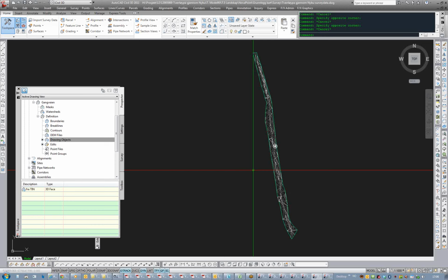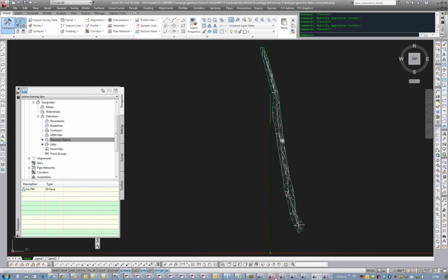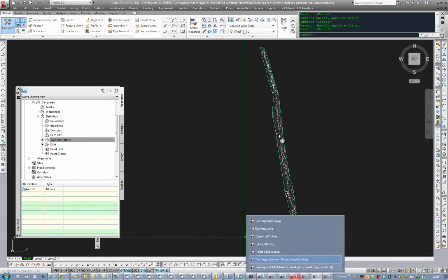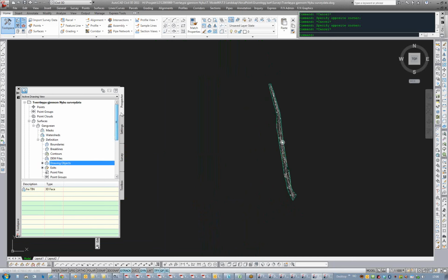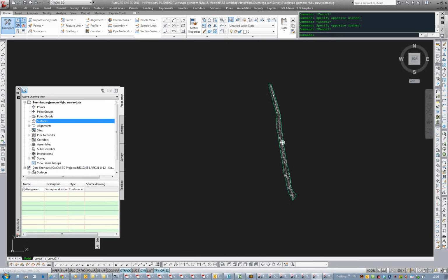Okay, so I should be going to a blank drawing now and data shortcut my base map, and then data shortcut my existing, and then put in my new in that folder, right? Yes. But you've got to create the data shortcuts folder first for this project. Where do I do that? In your prospector window, scroll down. It doesn't matter where or when I do that, right?